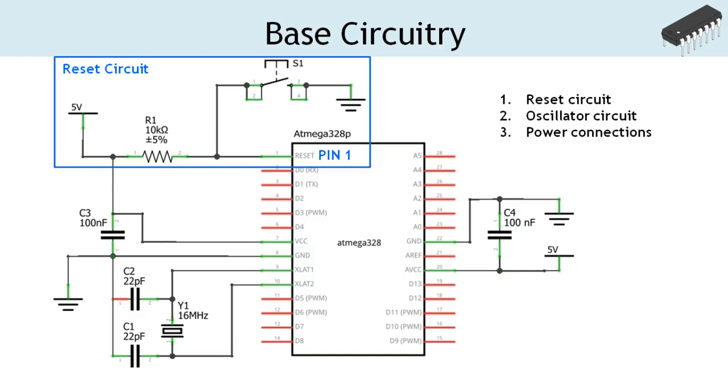The reset pin of the microcontroller is connected to 5V through 10 kΩ pull-up resistor, and it is also connected to ground via a button switch. When the switch is in off state, the reset pin is pulled high. The development board is reset by pressing the button switch. In the operation, the reset pin is short-circuited to the ground, providing a pulse of logic low and resetting the microcontroller.